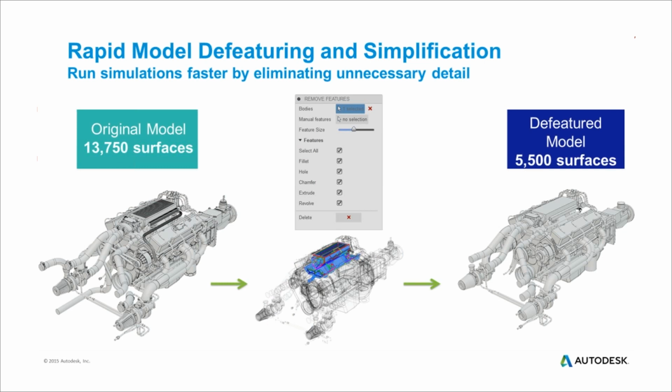And simplification shows up a lot in simulation because, again, you want to reduce the resources that your simulation is taking while preserving the fidelity of the results, right? This is an example from Fusion 360, in fact, where they're talking about defeaturing and simplification. The idea is still the same, but the original model had a bunch of surfaces over here, and using the simplification and defeaturing tools, they're able to get a much lighter model with about 5,500 surfaces instead. And that, again, frees up a bunch more resources and lets the simulation go a lot quicker, right?